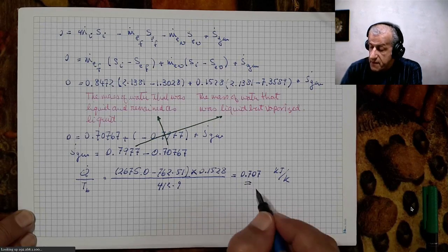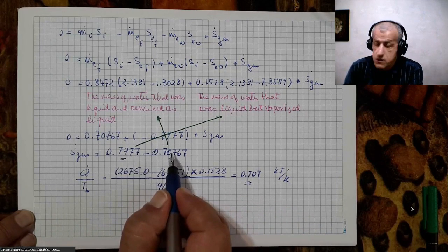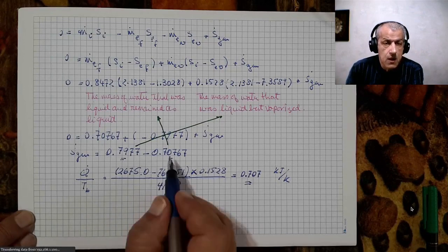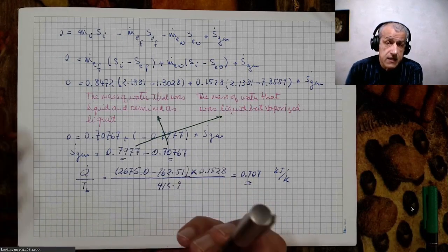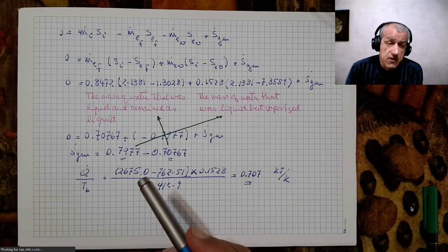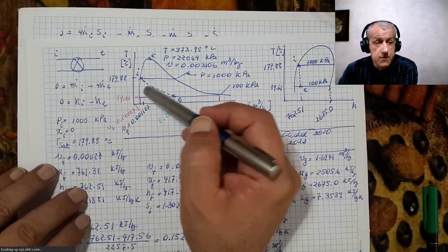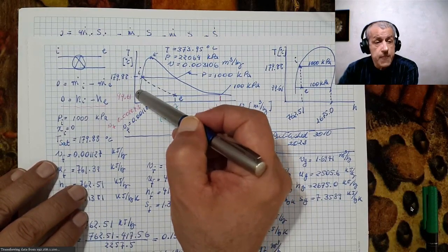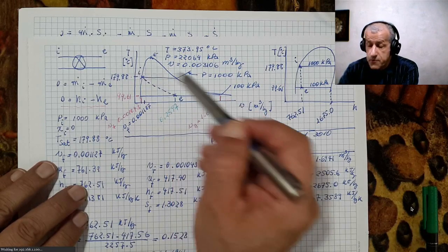This is a very comparable number to the numbers we have here. It's not exactly this one, although it looks very similar, and these are two different things. But certainly we can know that the change of entropy between saturated liquid at these two pressures is far less than the change of entropy that this liquid would require to vaporize.